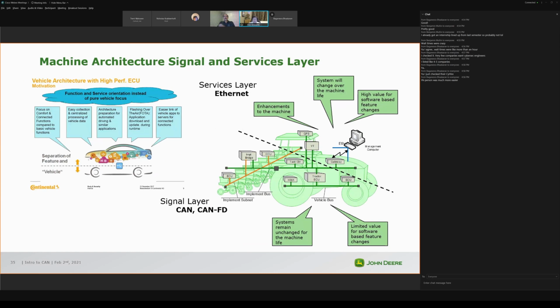The real-time control microcontrollers: it's much easier to find microcontrollers with automotive ratings, and automotive ratings, being temperature and reliability, are two big key things for a micro. Getting ones that actually support Ethernet is just coming out, or in the last few years is becoming more popular as automotive-style Ethernet becomes more widely available. So that's the other aspect of it, the availability of the parts, and cost always seems like maybe a reason that's not as prevalent or as much of an engineering basis.